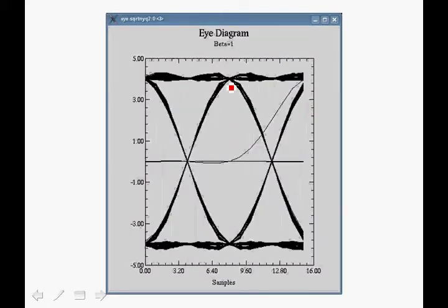By generating the eye diagram, by overlapping the signals over a fixed symbol period, we get the curve shown over here. And because of the 0 intersymbol interference characteristic, or the periodic 0 crossings that is characteristic of the Nyquist pulse shaping filters, we get this eye diagram where we see that we have 0 intersymbol interference and the eye is open. This is for 100% excess bandwidth.